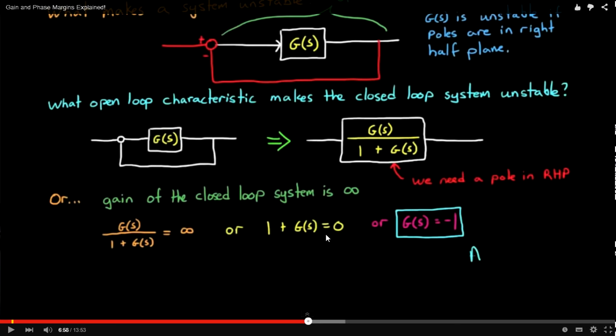This is an undesirable case. If it equals 0, it will go to instability. So you want to find the most unstable margin, I mean the unstable limit. In 1 plus G of S equals 0, you just bring this 1 over here, so G of S equals minus 1, that's all. This actually proves the previous video that I talked about, how we derive this.